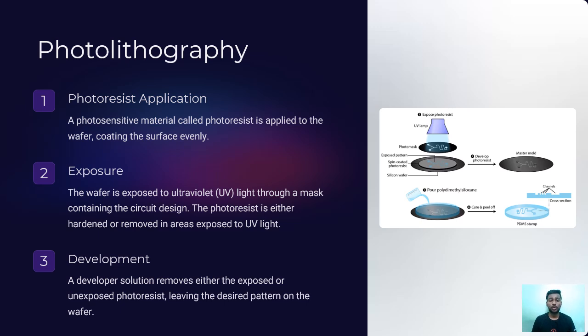The wafer is exposed to ultraviolet UV light through a mask containing the circuit design. The photoresist is either hardened or removed in areas exposed to the UV light. And development: a developer solution removes either the exposed or unexposed photoresist, leaving the desired pattern on the wafer.